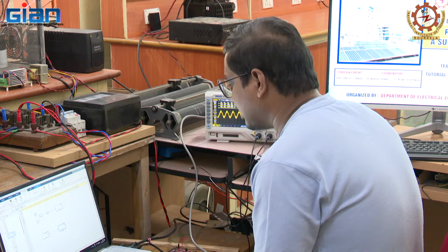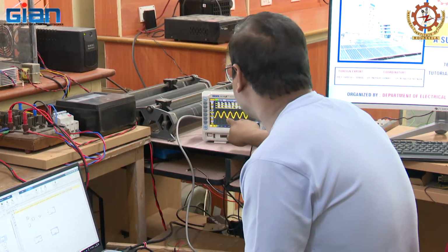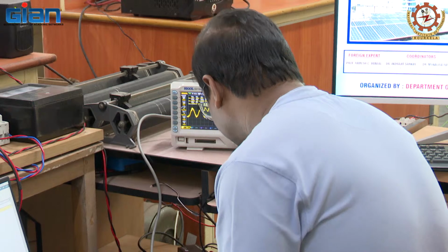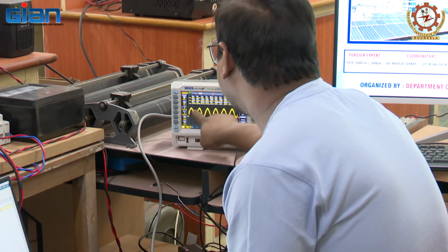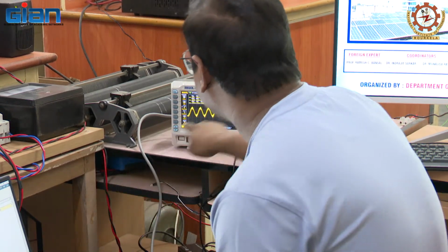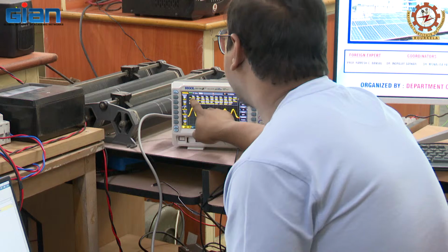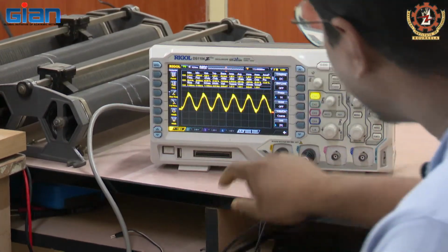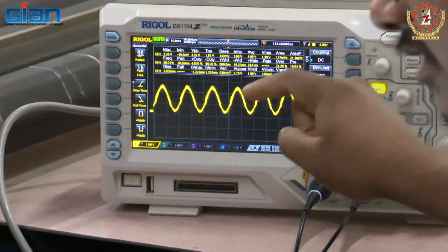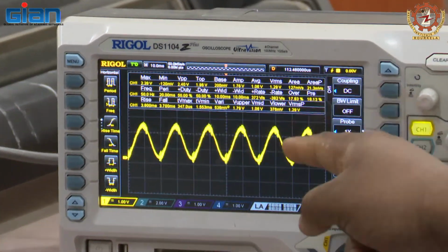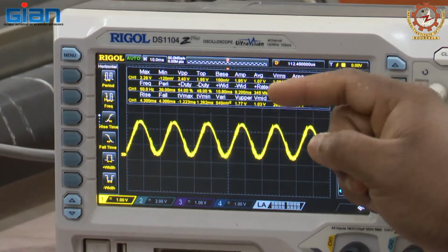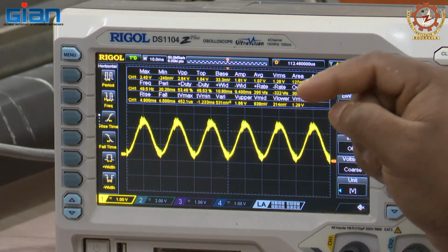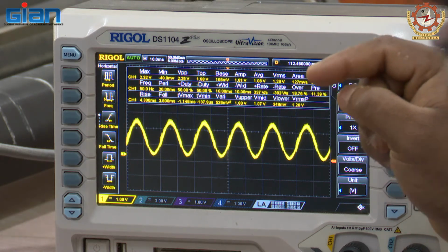See, we are able to read this DAC B. I have connected across DAC B, so we are able to read this DAC here. Similarly, you can see the sine wave signal that we gave from the DAC, we are getting here. See, the maximum value is 2, the minimum value is 0, and the frequency is 50 Hz. So we are able to read this sine wave now from DAC B. That means my ADC is able to read the analog input, and that has been given to DAC B.